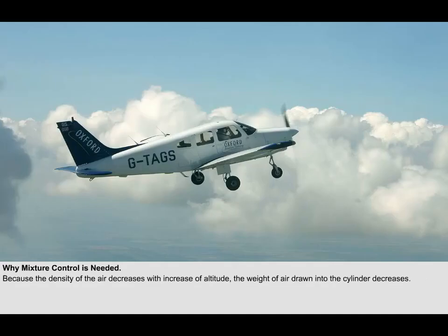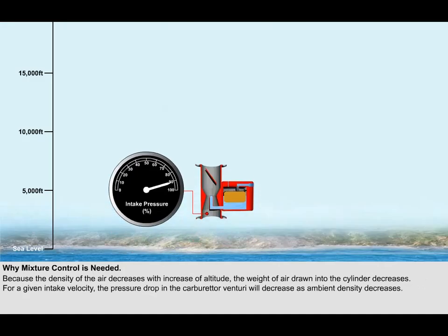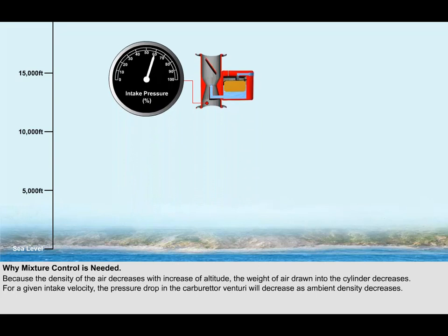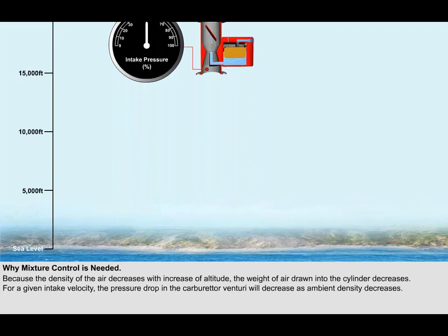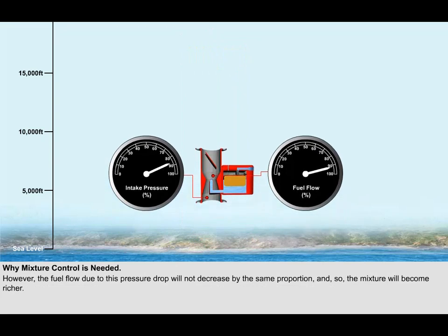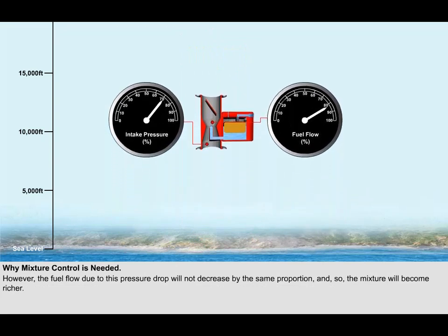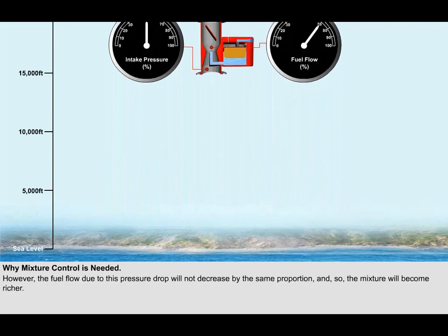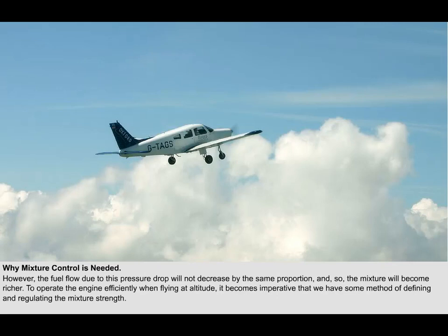Because the density of the air decreases with increase of altitude, as the aircraft altitude increases, the weight of air drawn into the cylinder decreases. For a given intake velocity, the pressure drop in the carburettor venturi will decrease as ambient density decreases. However, the fuel flow due to this pressure drop will not decrease by the same proportion, and so the mixture will become richer. If we are to operate the engine efficiently when flying at altitude, then it becomes imperative that we have some method of defining and regulating the mixture strength.